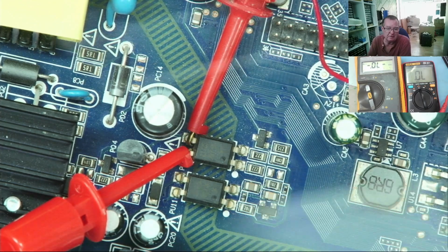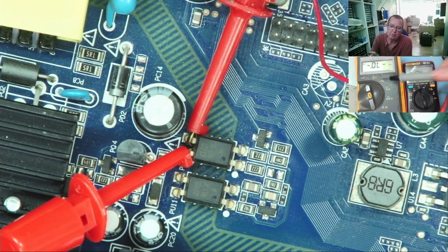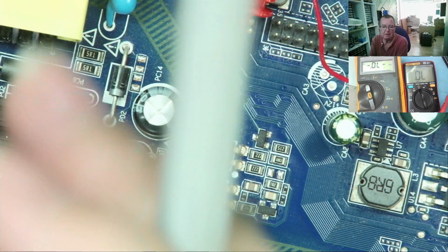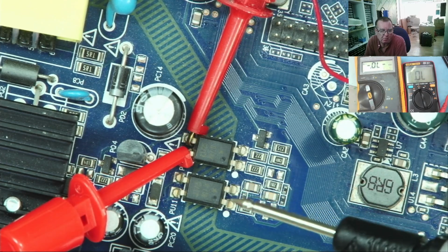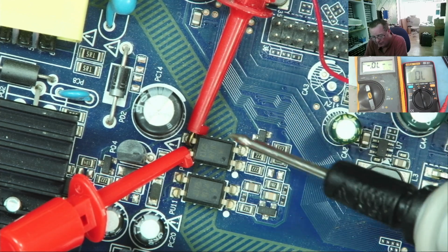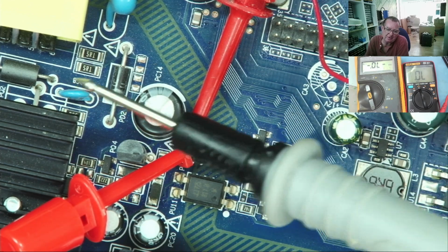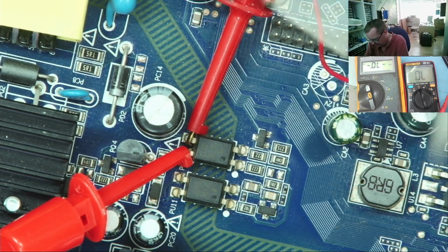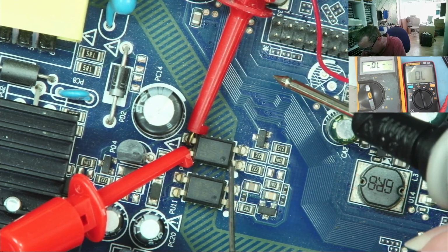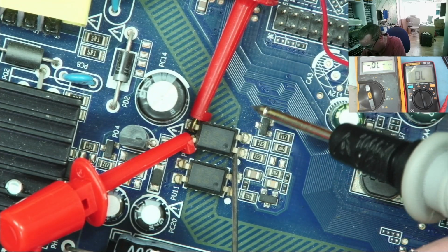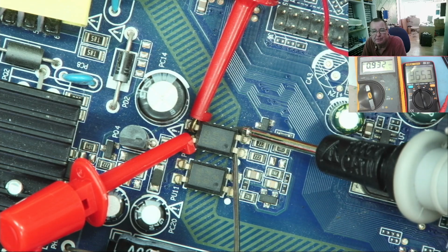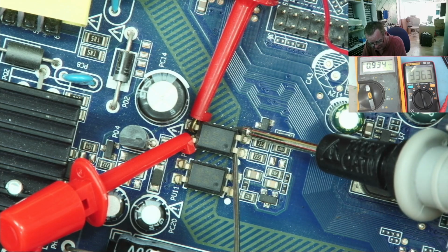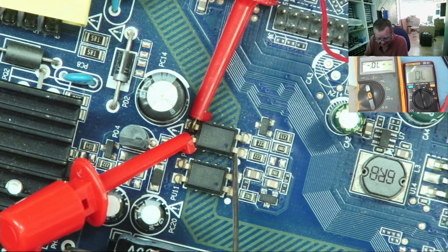At the moment, this is in resistance range. This one is in diode mode. I have separate red and black wires now on the Fluke. They're not connected, the two blacks together. Because this is an opto isolator, it isolates, so the ground on this side of the circuit is independent of the ground on that side. That's what it's supposed to do. So watch what happens now if I use diode mode to turn the LED on. Well, you can see 9.2, 9.3, that's the diode, and you can see the resistance is lower on the Aneng.